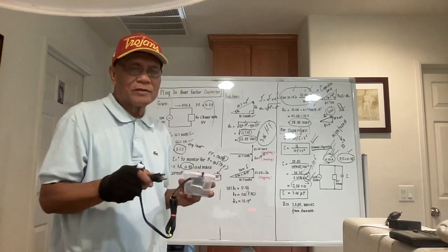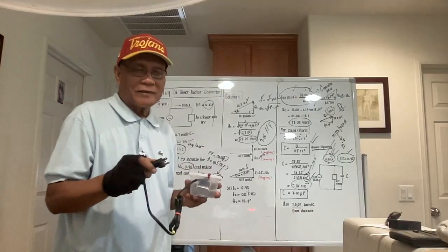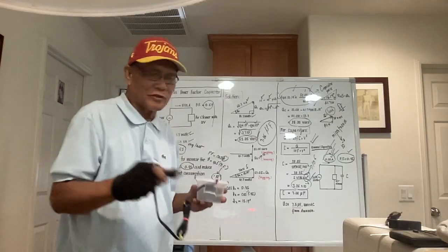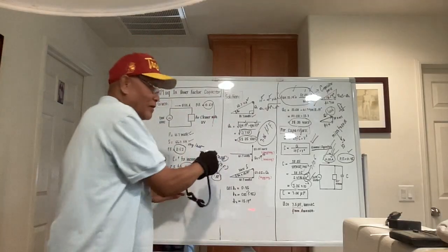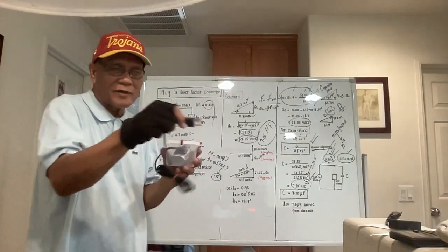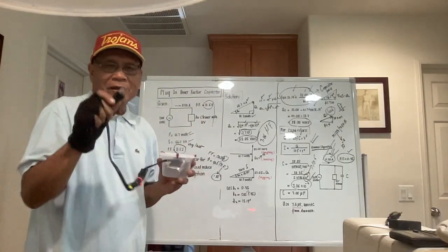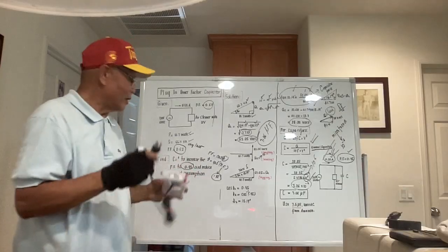For standalone motor loads, if we know that the current consumption of that motor load is big, you could follow my lecture here, compute for the required C, and plug in this capacitor beside your standalone motor, and for sure your current consumption will be less. And your power factor will rise up.